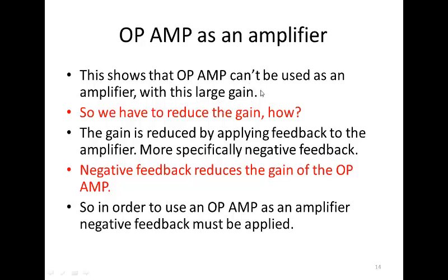Keeping the input signal in microvolts is very sensitive. The signal becomes very sensitive to noise, and it limits the range of the input that we want to amplify. That means we cannot amplify signals having magnitudes of millivolts or in the volts range. So how can I use the op-amp for signals in the range of millivolts or volts, and amplify them using the op-amp?